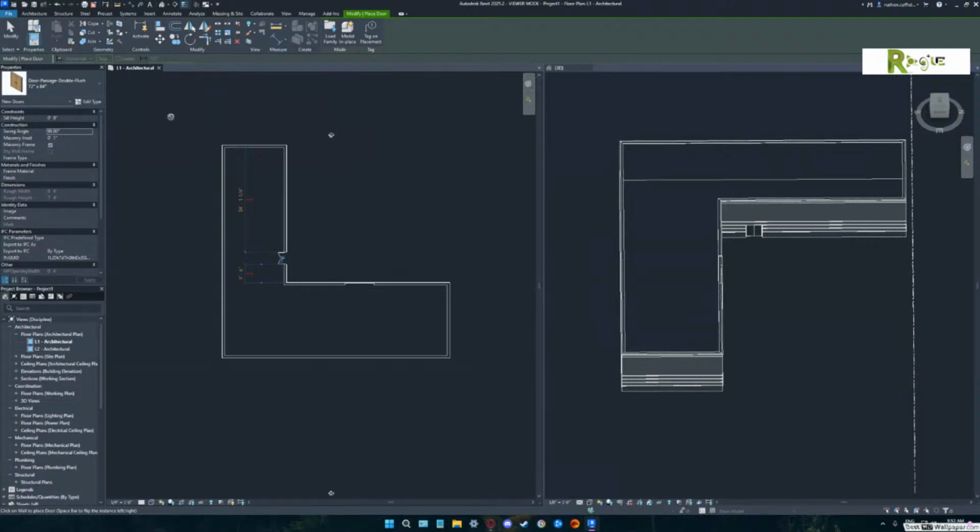But what we do is, if that family, a garage door, is not in our project, on the top bar, the third one from the end says load family. No, I'm sorry, our main tool palette. Third one from the end on the other end is load family. Look on the right side. There, got you. Don't be sorry. It's better that you have to search for it, because that's what other people are going to have to do. So we say load family.